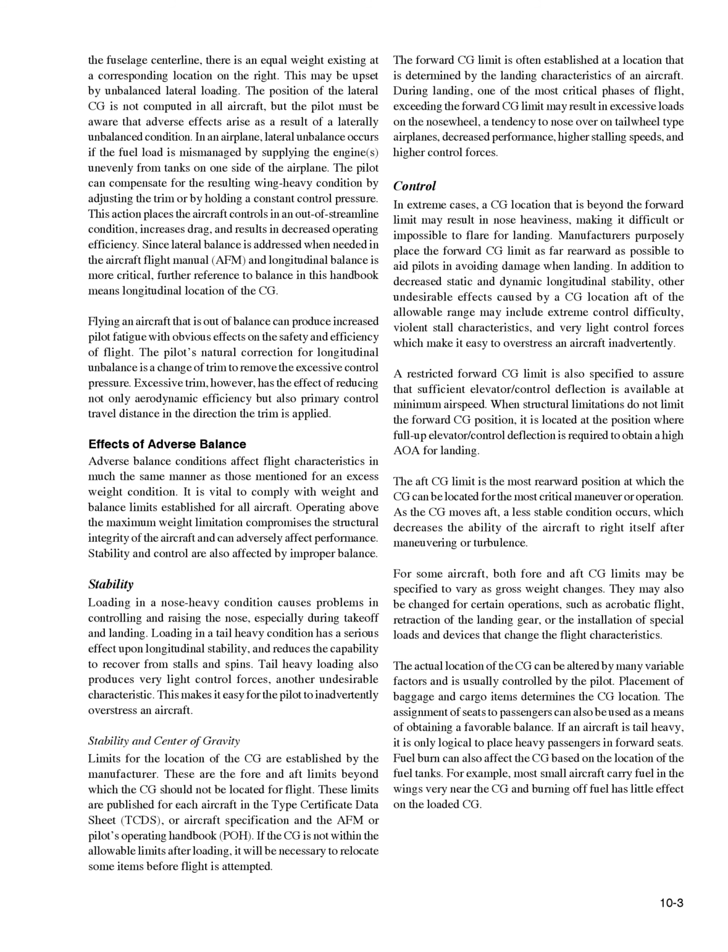Loading in a nose-heavy condition causes problems in controlling and raising the nose, especially during takeoff and landing. Loading in a tail-heavy condition has a serious effect upon longitudinal stability, and reduces the capability to recover from stalls and spins. Tail-heavy loading also produces very light control forces, another undesirable characteristic. This makes it easy for the pilot to inadvertently overstress an aircraft.